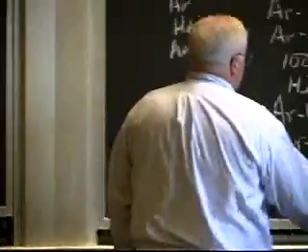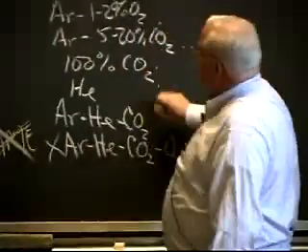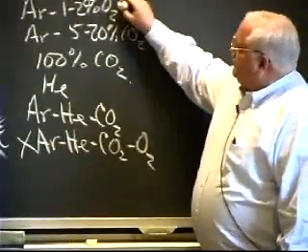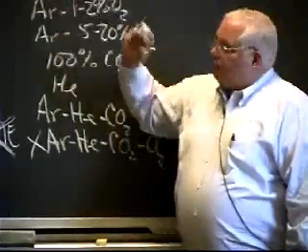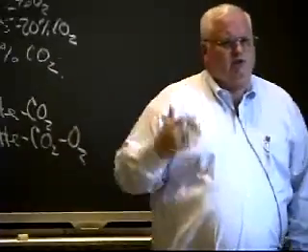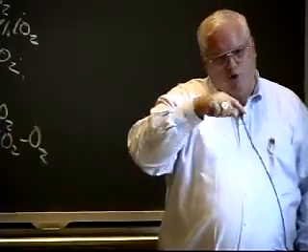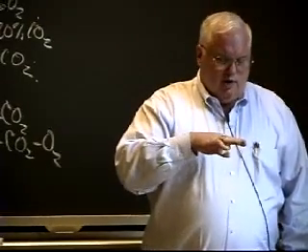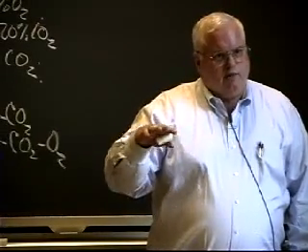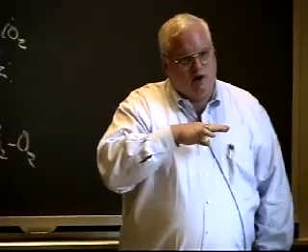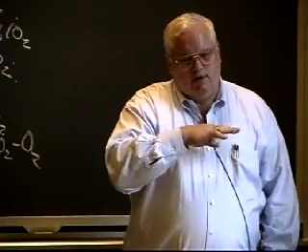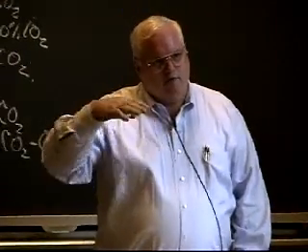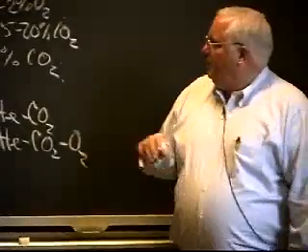Actually, anyway, why do I use all these different things? It turns out if you try to use pure argon with carbon steel, the arc's not completely stable. It'll leave a rough weld bead. If you add just a little bit of oxygen, it seems to run smoother. In fact, you can hear the arc. It is a smoother sounding arc. It doesn't have little crackles and pops and stuff.